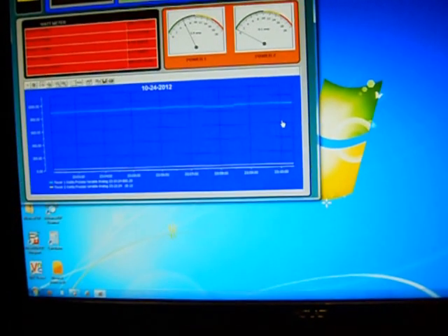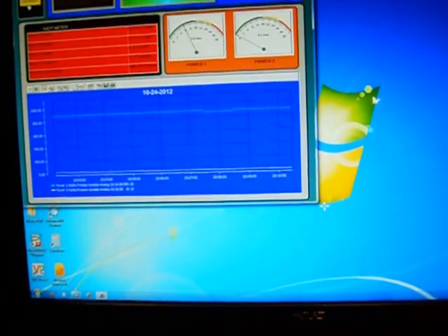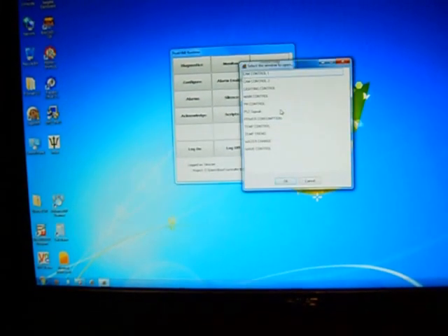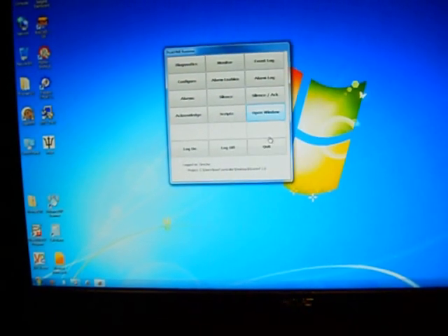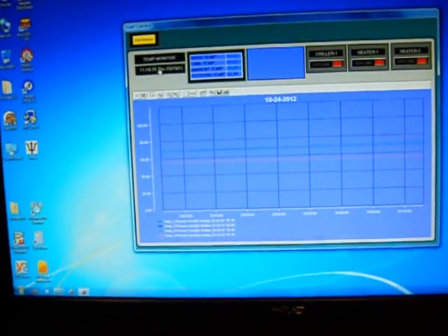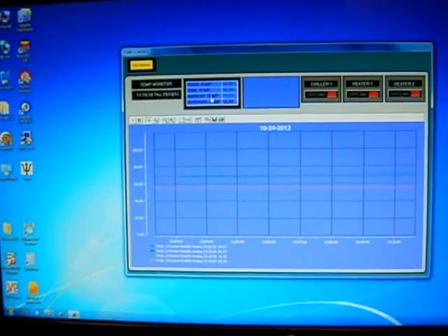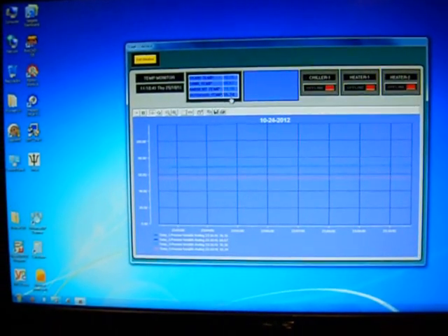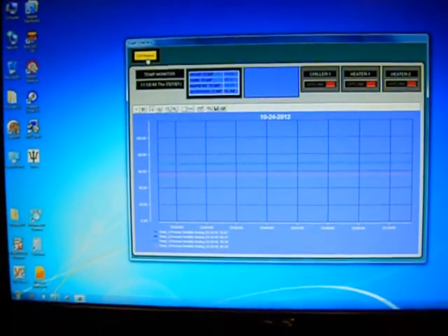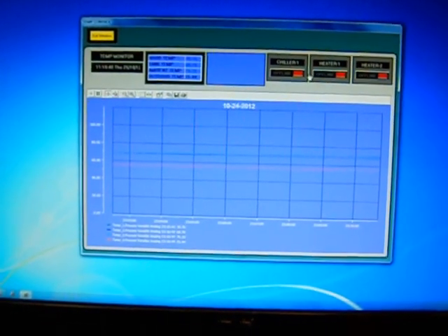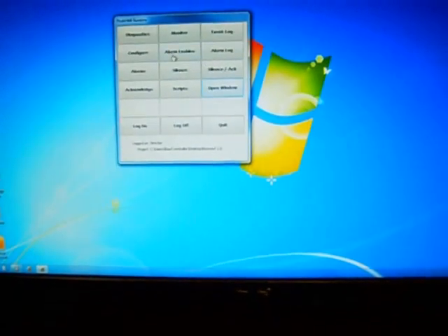Here's for the power consumption, which is a couple CTs through an analog circuit. Some temp trend, which measures the hood temp, the tank, the ambient temp inside the cabinet, and then of course outdoor temp, just for reference. And these are some interface with the heaters, chillers, things of that nature.